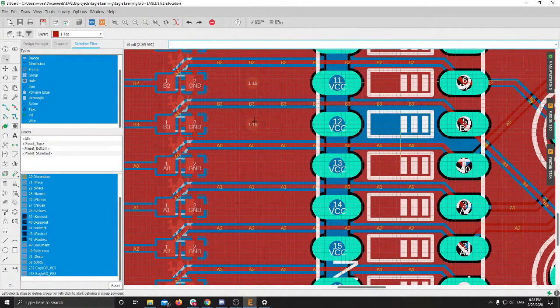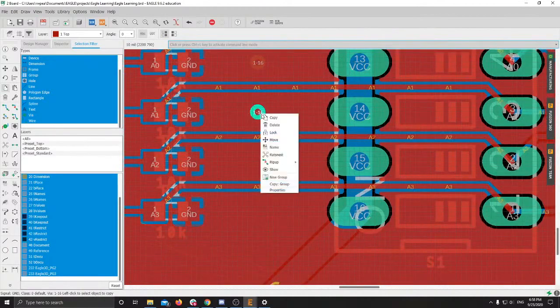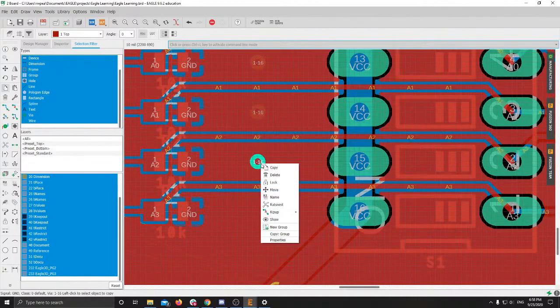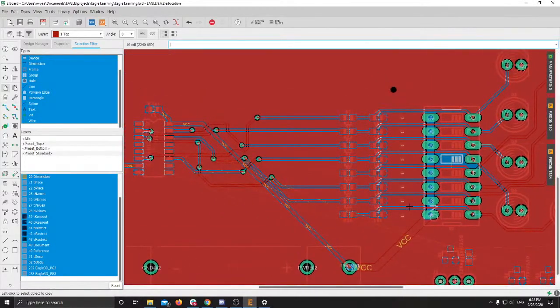So again, that's probably easiest to do more towards the end, but good to keep in mind and important to do so that your ground planes are actually connected everywhere. Because otherwise you can end up with stray capacitance between certain ground connections and whatnot, which is bad for your design.